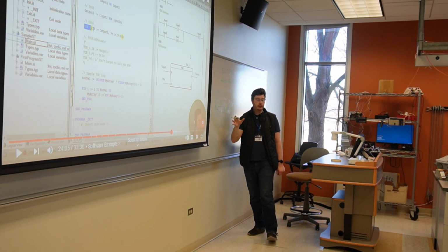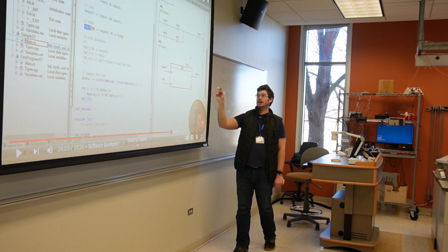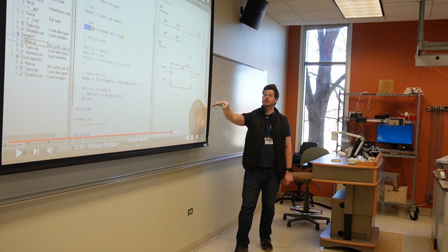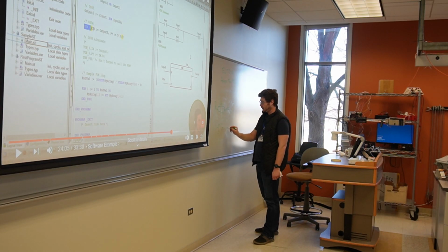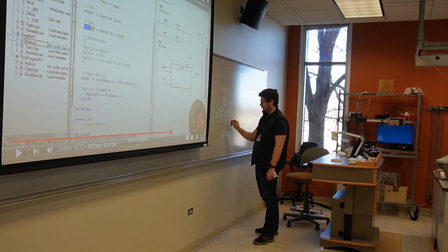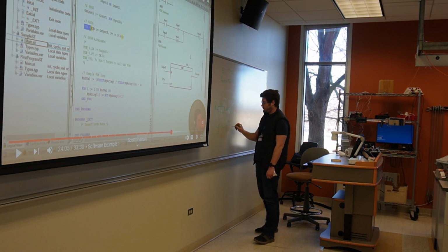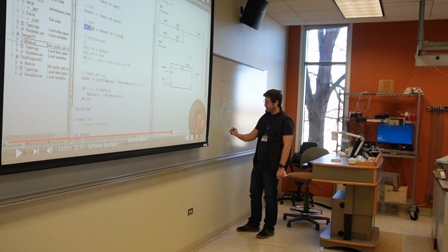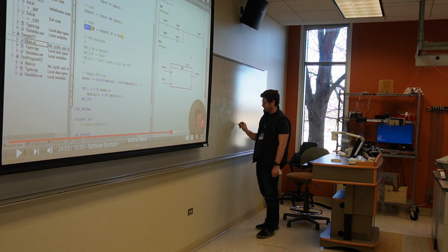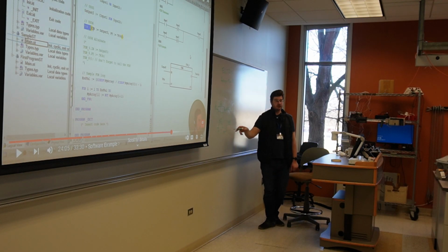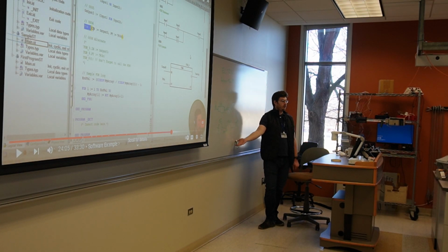Something that we'll do later is you could have this T-on block in ladder logic or a function block diagram where you had your button on the left, your contact, you would wire it into your T-on block. And for example, if you wanted something to happen 5 seconds after you touched a button, this is how you would do that. If you wanted to turn on motor 1 5 seconds after you press the button, like so.